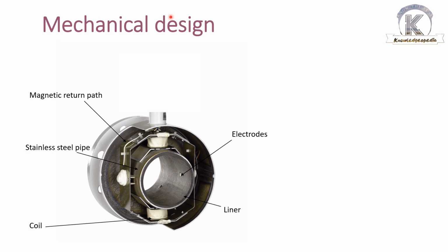Anyway, so now I'm coming to the electrode section. These are the two electrodes, as I already showed you last time how the electrodes are placed in a flow meter body. That is to detect the measurement signal, and it must be resistant also against the medium. Several materials are available as the standard option, like stainless steel, alloy C22, monel, tantalum, platinum, rhodium, etc. So different options are there.